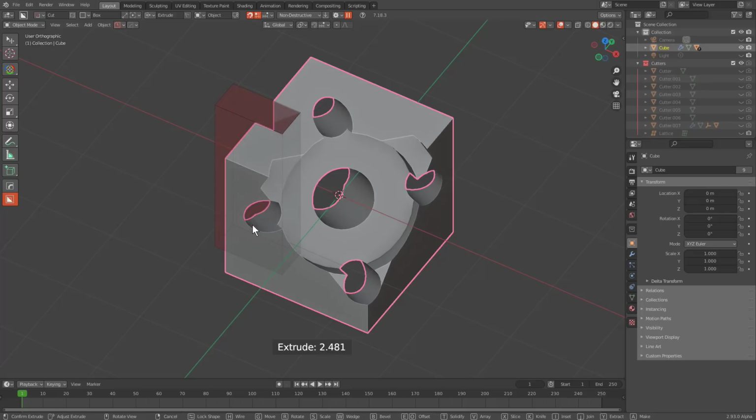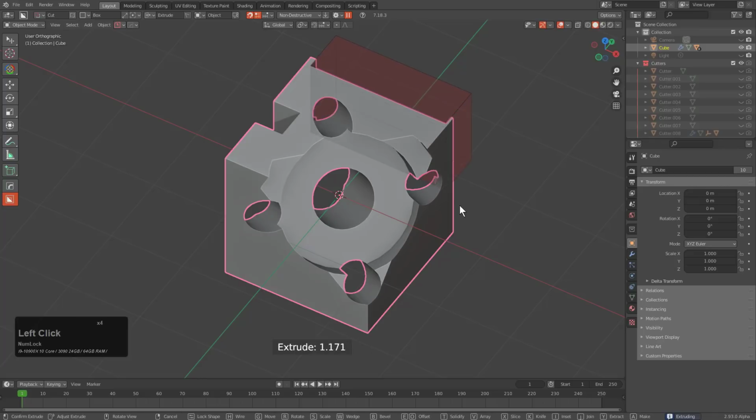So this is something we still aim to resolve and have even better in future updates, where Extrude System B will possibly only show up in the event of certain view vectors being aligned perfectly head-on, versus a surface where you're looking at it from a corner and it's definitely obvious that Extrude System A would preferably be used in this situation. But this is something that we'll continue to be working on over subsequent versions of Boxcutter, but just letting you know that improvements have been made in this regard for this particular update to make view extrusion as easy to toggle between as possible.